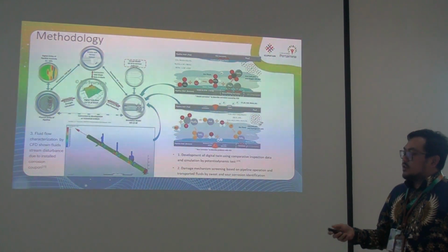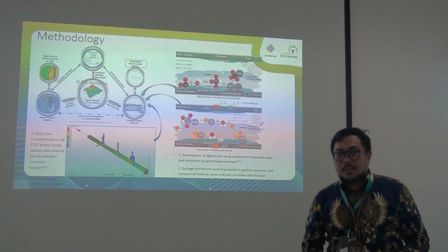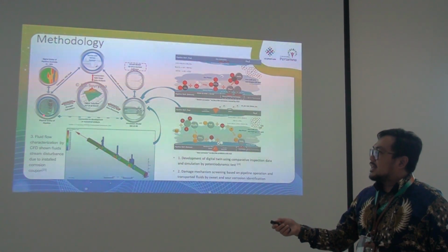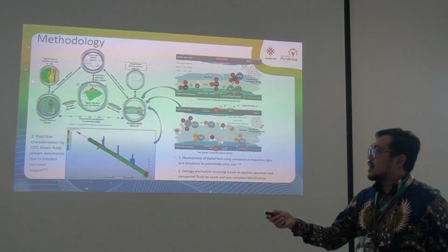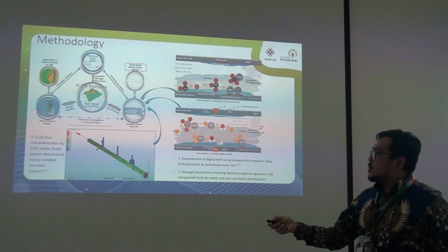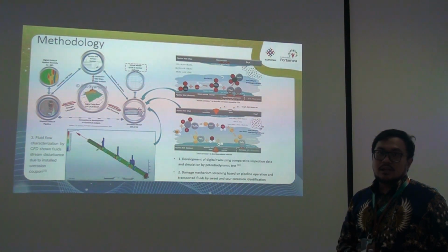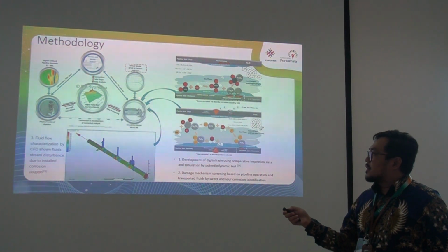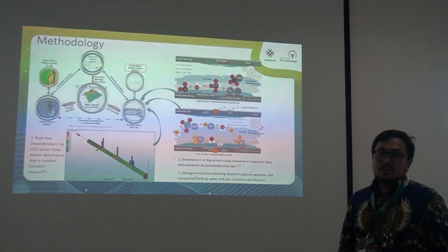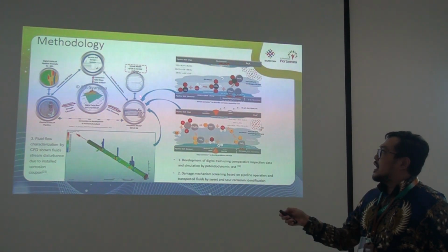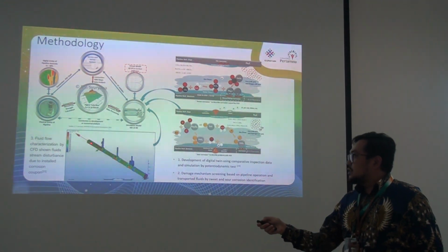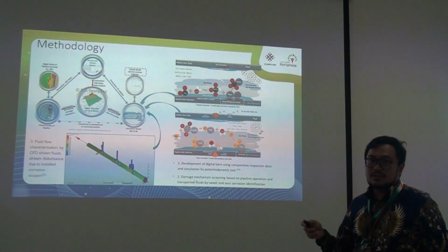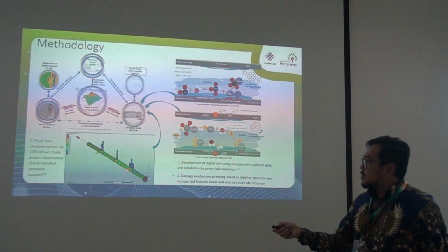This is our methodology to identify the digital twin. We start from the damage mechanism. We have the MFL color contour. We copy the condition of the damage mechanism morphology, and we copy it by using the potentiodynamic galvanodynamic test, and we have data to use for the characteristic. Also we consider using computational fluid dynamics to identify the flow condition.